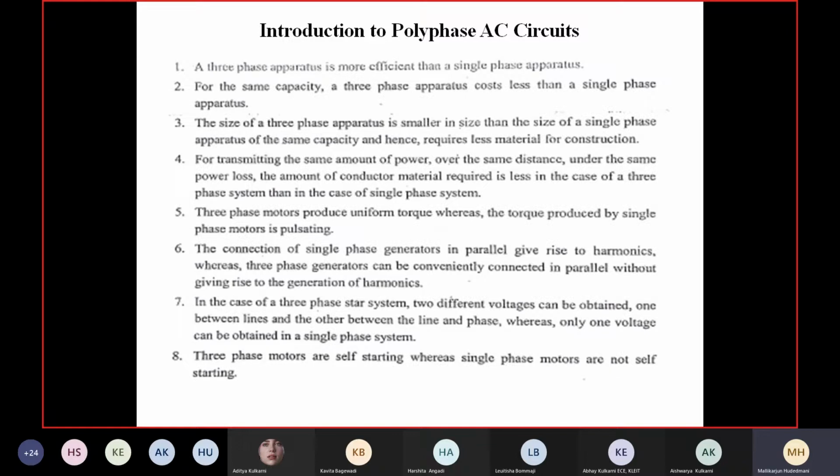Now look at a farmer. A farmer in the house has a water pumping application. Say he requires a 10 HP motor connected to a pump to pump the water from underground to the farm. Then for 10 HP he may choose three phase or single phase. Definitely, we know a 10 HP single phase motor, if I purchase it, is costlier and bulkier, larger in dimension. When the size of the machine increases, the investment in developing that material also increases: casting of the motor, inside winding, insulation, stamping, shaft, all interconnected mechanisms involved cost you more.